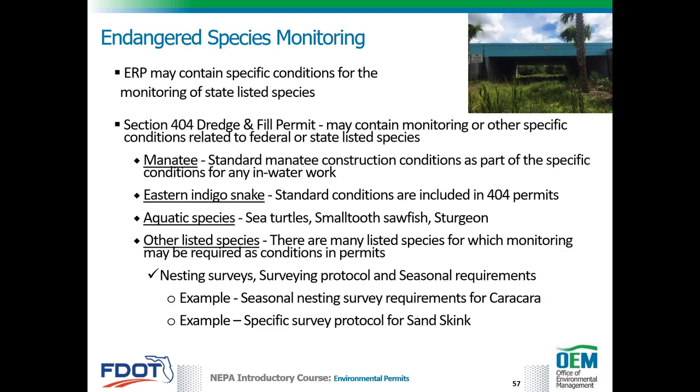Many state-issued ERP permits include specific conditions for the monitoring of state-listed species. Similarly, the Section 404 dredge and fill permit may include monitoring or other specific conditions related to federal or state-listed species. Several threatened or endangered species occur throughout the state, including coral species on bridges in South Florida, sand skinks on the ridge in Central Florida, and listed mussels in Northwest Florida.